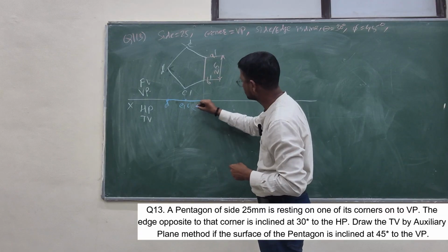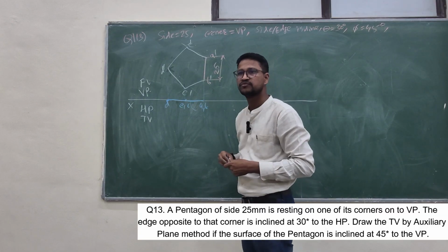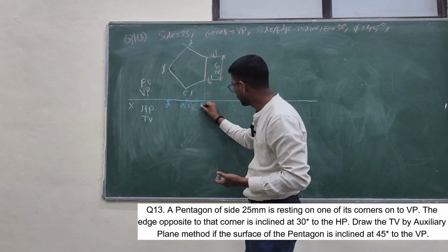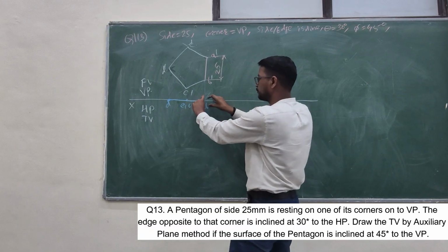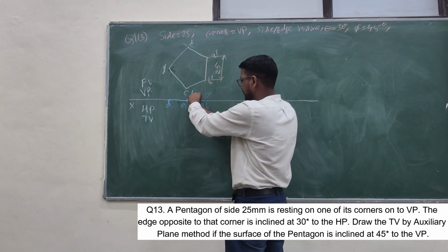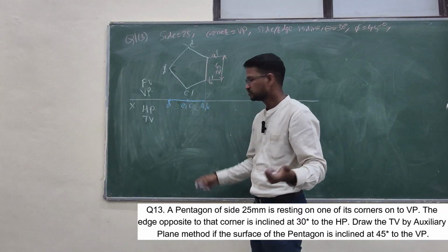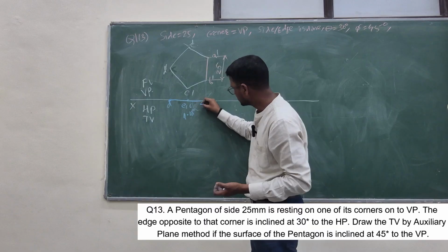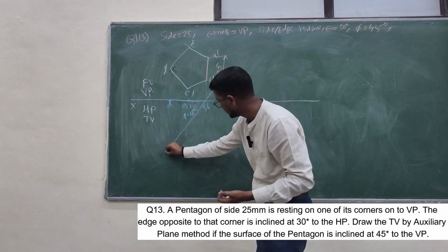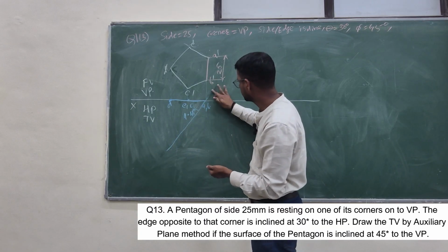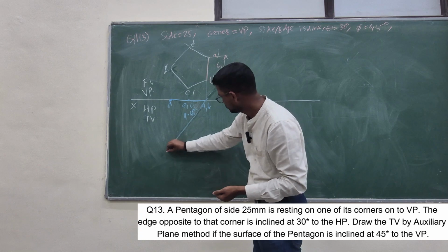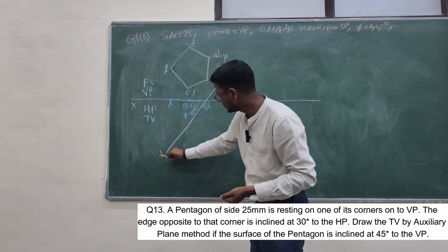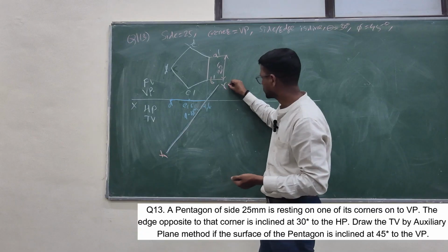I will take an inclination. How much is this inclination? 45 degrees, from which point? From point AB. Now put the protractor at point AB and make the inclination 45 degrees. So phi is equal to 45 degrees from this side. When I draw this line, wait, I will change to a different color. So this is a new reference line. This new reference line is known as the X1 Y1 line.